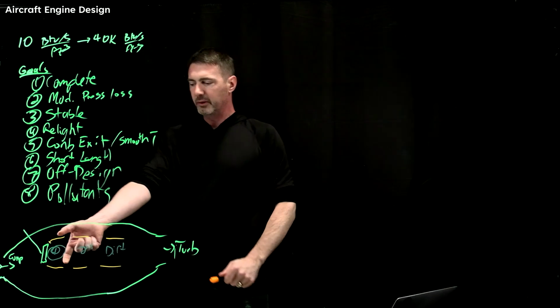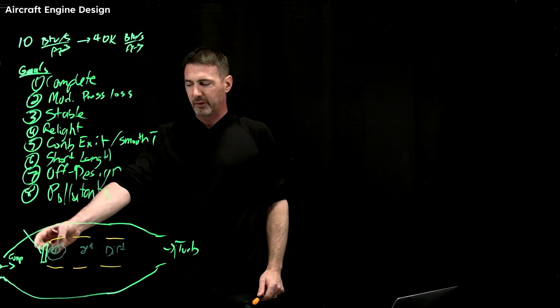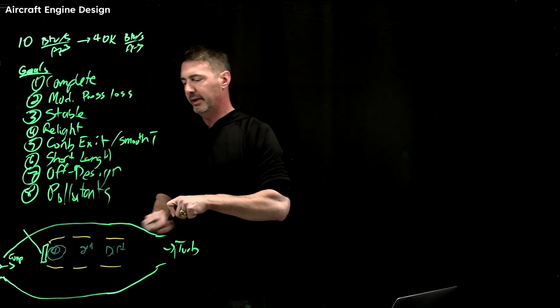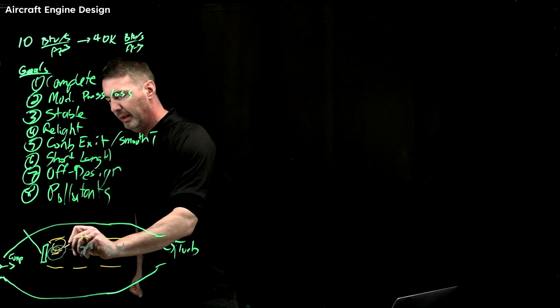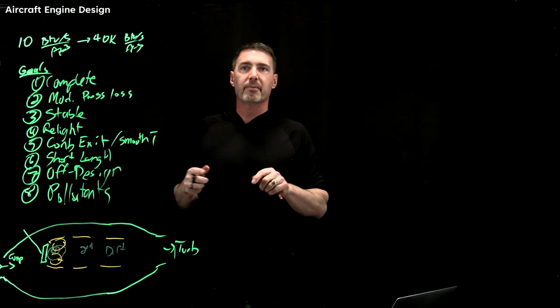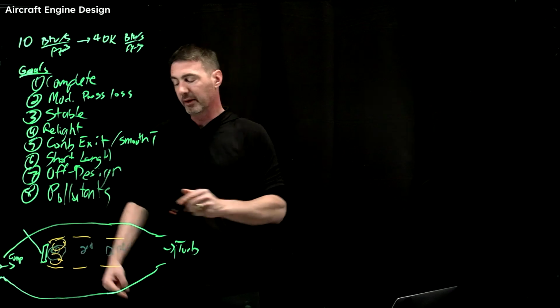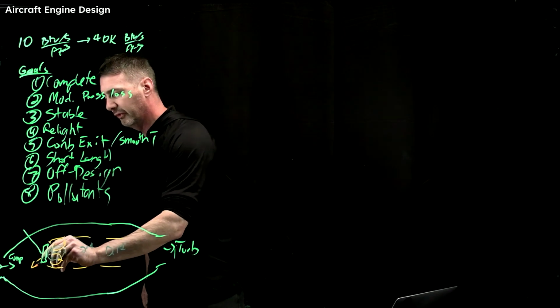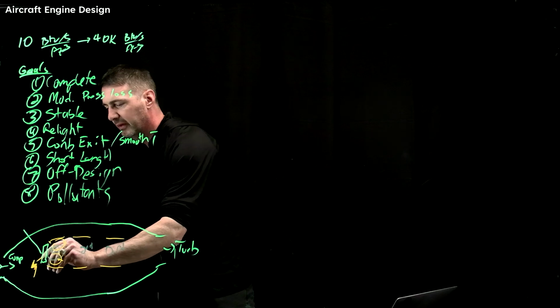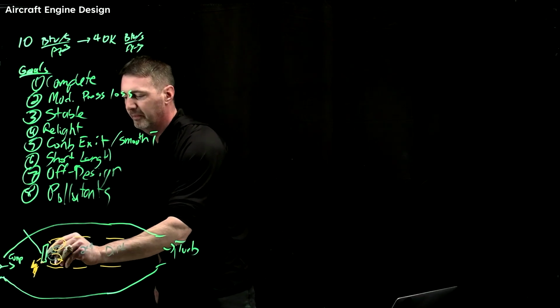Now, a lot of times what they do here, this is where the fuel is coming in, and they'll put a lot of swirl here. And so really what you're creating is a recirculation bubble. And the book does a good diagram of all this. You're creating a recirculation bubble for the flame to hold. Now, also through here is where the spark is going to be. They'll draw a little lightning bolt. Okay, there's my lightning bolt. So spark is going to come in there and light this.